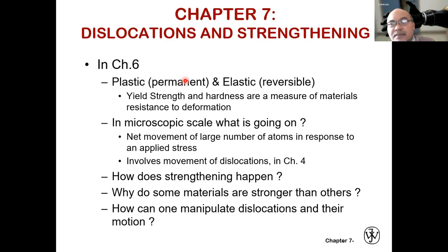Slip occurs, the slip between the planes occurs, and when the load is released, while the distance between the atoms may come back to its original state, the slip cannot come back to its original state. The slip between the planes is a permanent deformation. So this makes them stay in that plastic deformation shape. The deformation that occurs cannot be reversed, so it makes permanent deformation.